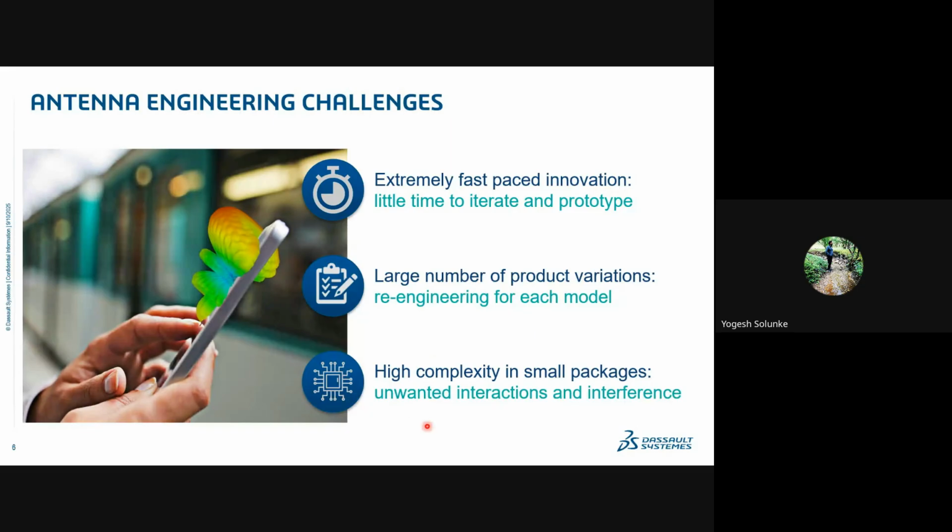This is related fully to electromagnetics, as we have seen in this example, a mobile phone, which is backed by multiple RF units, multiple antennas, multiple PCBs, and the casing of the mobile itself. All these are electromagnetic absorbers or reflectors, I can say, which cause electromagnetic interference. Once you have excited an antenna, the fields will radiate, and due to other conducting elements, that field will be coupled into them. We need to take care of that, which is the biggest challenge when we design any RF component, in the electromagnetic field interference case. So these are the three listed challenges.